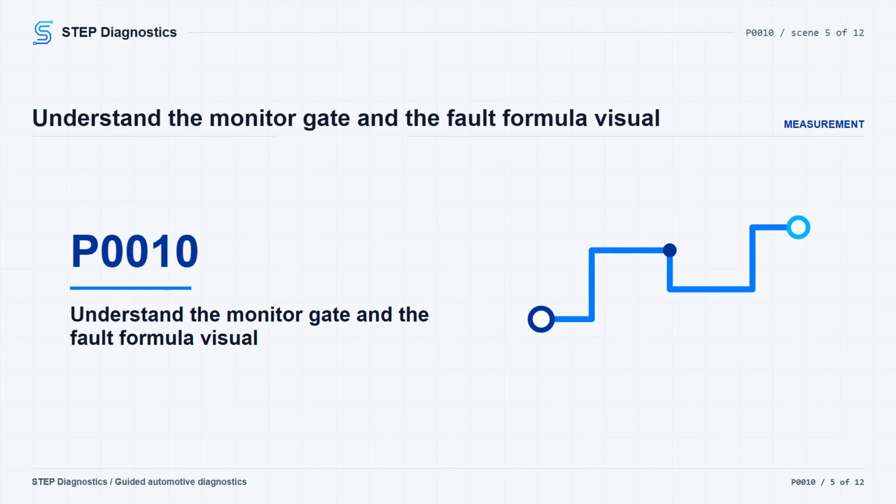For this monitor, the ignition voltage condition is greater than 11 volts. The switch is in run or crank, and the camshaft position actuator solenoid valve is commanded on. Once the running conditions are met, the monitor runs continuously.